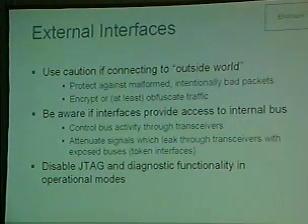An example of this is, Brian will actually give you an example. Yeah. One example is token interfaces. A lot of times you'll have an iButton or some type of data key, like in an STU phone, that'll have access to the internal buses, and many times you should obviously gate those buses properly with a transceiver. I don't know if too many people know, but a lot of times, even through transceivers, there's leakage, and if you drop a couple of low ohmage resistors in line with those data lines or even address lines, you can prevent leaking. It's not really a covert channel, but you can prevent bus leakage that way.